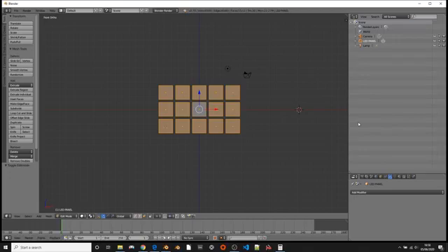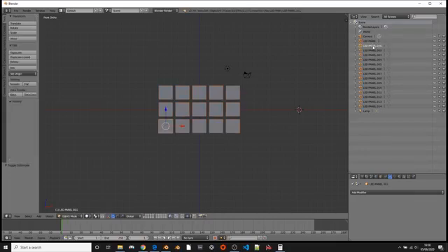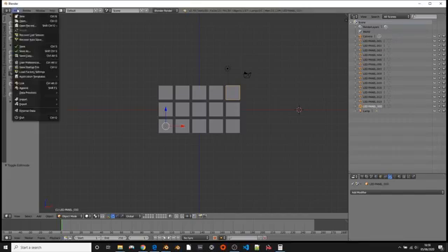And there's a few ways this can be useful to us in AI. So, P by loose parts and select that. There we go. So you can see now that it's done all of those for me. Now what I want to check, I think it's done the right thing. Yeah, there we go. Because it's actually numerically numbered those, I'm going to just change that first panel name just so that it is in line with that, because that was quite nice. Let's call it 000. There we go. Okay, cool. So now I'm going to export.